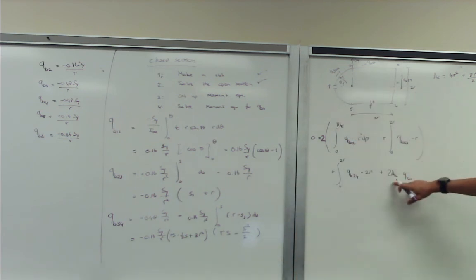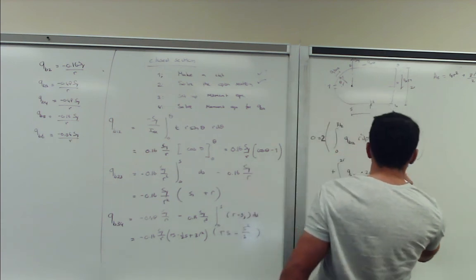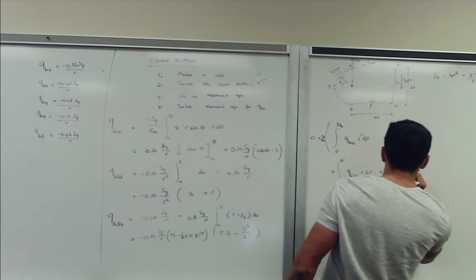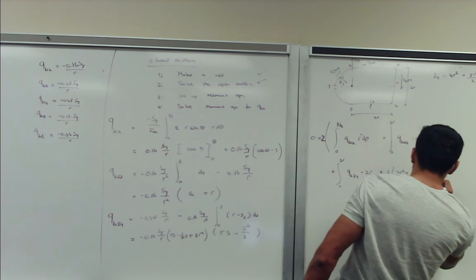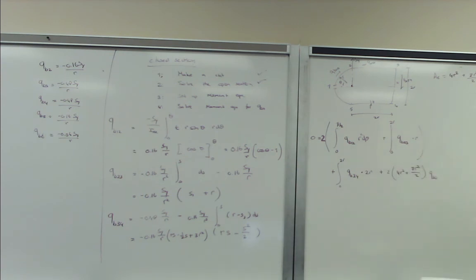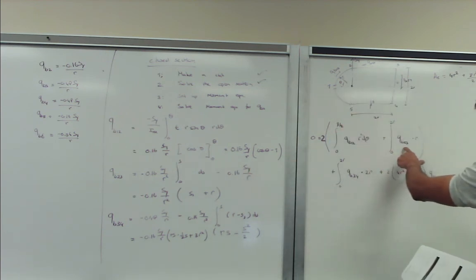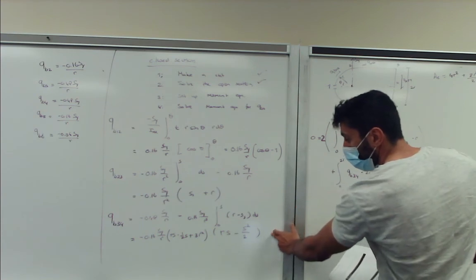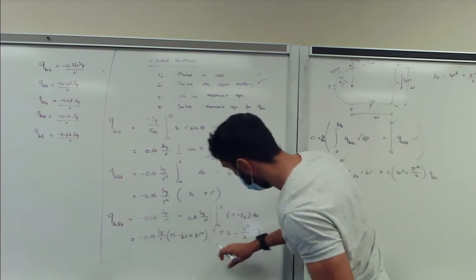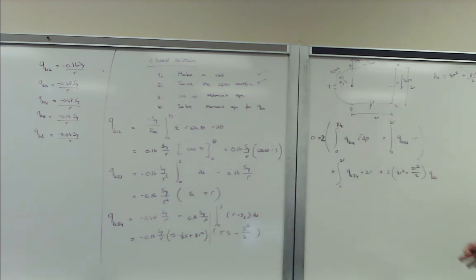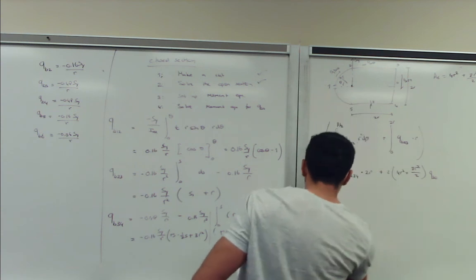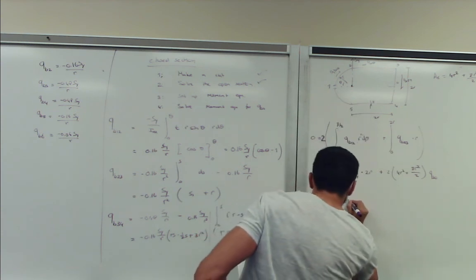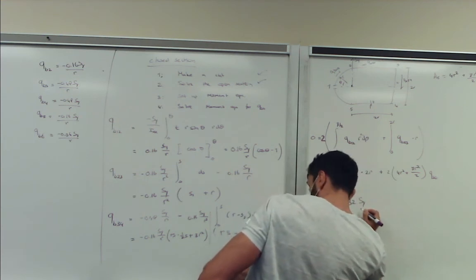So now we plug in this equation, the enclosed area here. So we say that we have 2 times 4R squared plus pi R squared over 2 times QS0. As stated before, the equation for 1, 2 is given here. The equation for 2, 3 is given here. And the equation for 3, 4 is given here. This one is part of this integral. So now you evaluate the integral separately, and you have basically known numerical values and one unknown. So now you can solve for QS0. QS0 is equal to 0.23 SY over R.